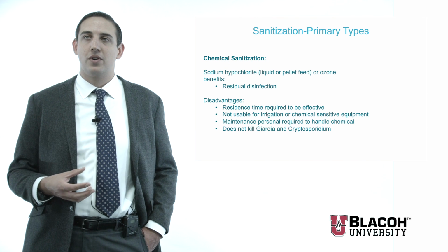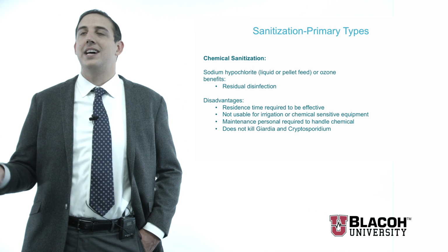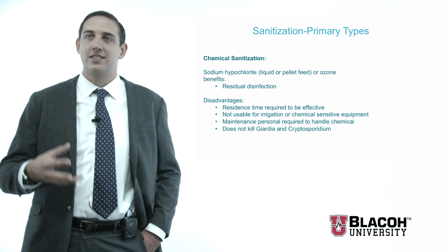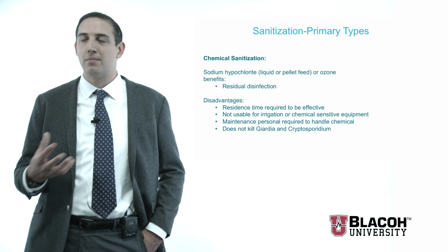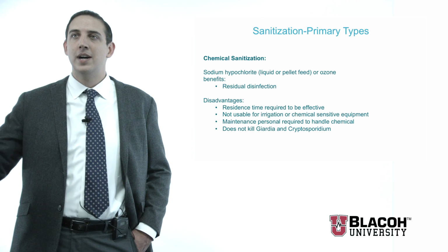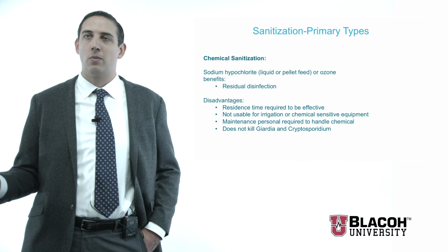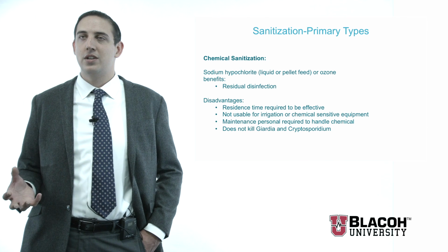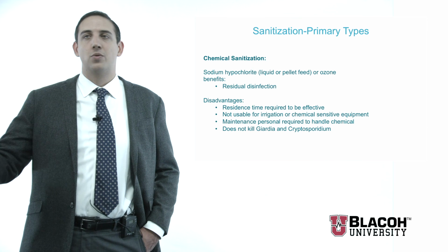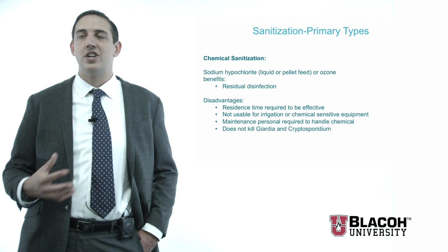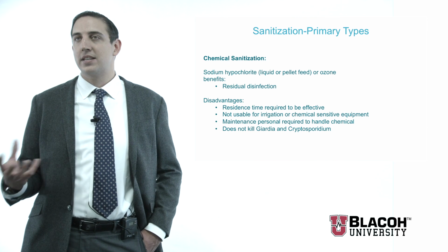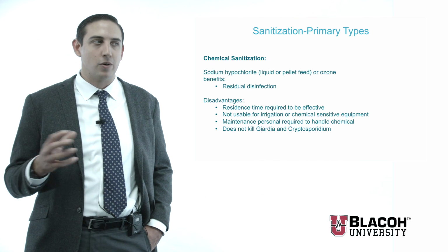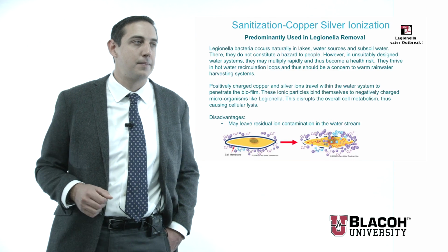Its one benefit over UV is that it has residual contact time. If I chlorinate something, it can stay clean for as long as the chlorine is still in the solution. The problem with UV is once I pass through it, if I reintroduce a contaminant into my water stream, I now have a situation where there is no residual treatment. You pass through the UV, it's a one-shot kind of deal in that case. So you have to look at what is ideally best for your application with a chlorine or UV sanitization.